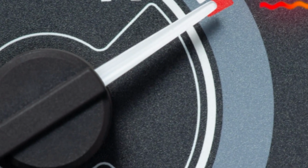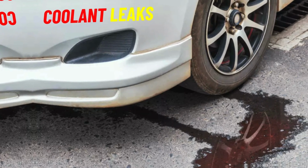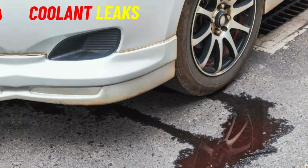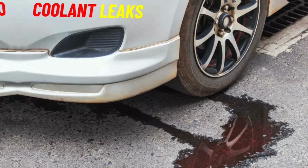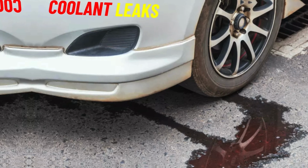Number 2. Coolant leaks. A leaking radiator can result in coolant dripping or pooling underneath the vehicle. You may notice puddles of coolant when the car is parked. Coolant leaks can occur from cracks in the radiator tank, damaged hoses, or corroded fittings. Loss of coolant can lead to overheating and potential engine damage if not addressed promptly.